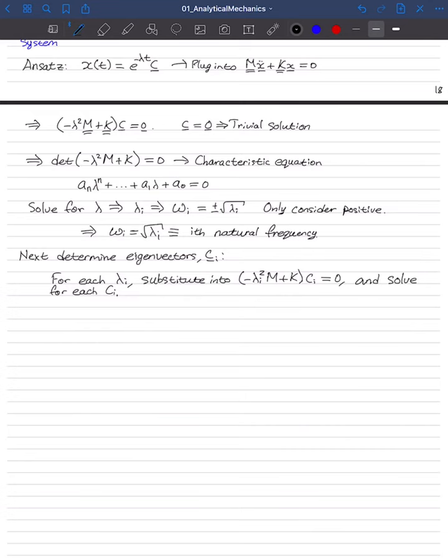So a normal mode has both a natural frequency and a mode shape that must be included. If you want to talk about a normal mode, you have to know the natural frequency and the mode shape. Okay, at this point we've now successfully solved the eigenvalue problem. The next step is going to be to mass orthonormalize those mode shapes.